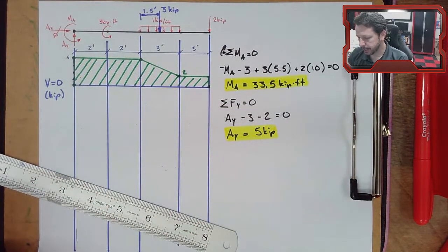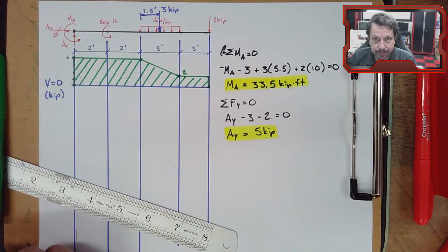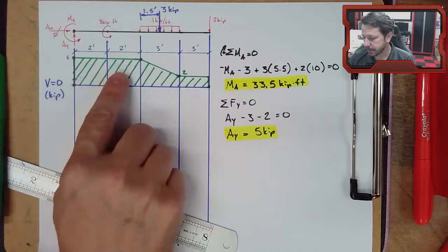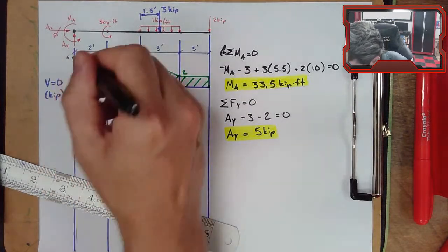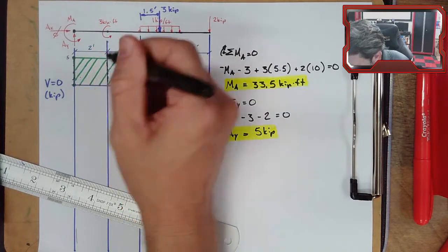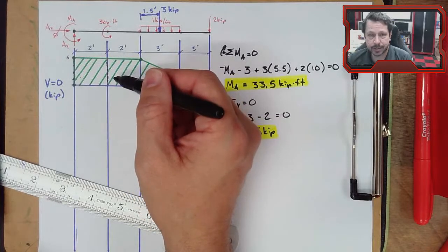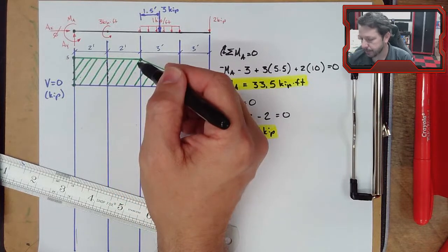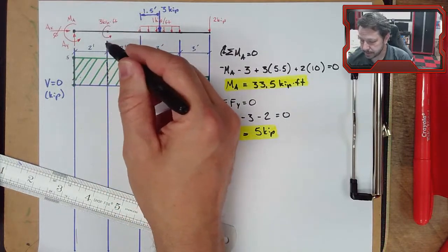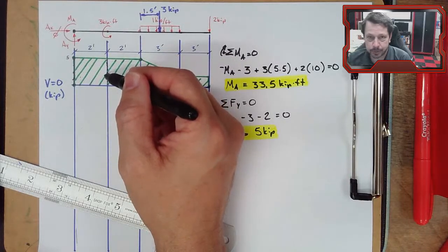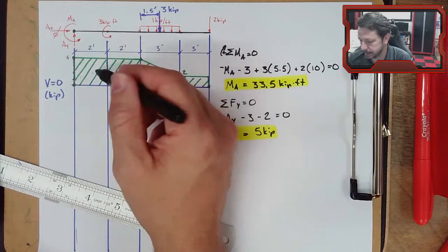And I need to go ahead and divide it into the individual pieces. And I need to basically integrate this, so I need to calculate all the areas under the curve here. I do need, this is why I draw the guidelines, I do need to remember this is 2 separate areas. I can't treat it as one 5x4. I have to treat it as 2 5x2s, because this concentrated moment is going to interrupt what's going on in my moment diagram, and then we'll get back to what I'm doing. So I need to break these into 2 separate ones.